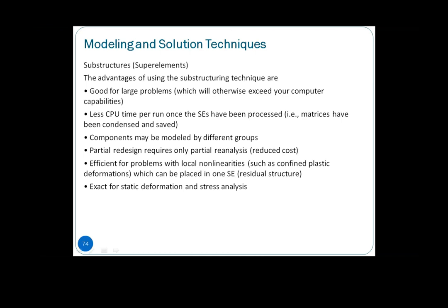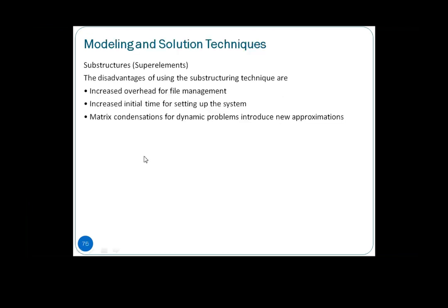So it will be good if you are looking into static deformation and stress analysis. If you are using subcomponents, they can be separated quite well and analyzed separately, individually. But there are disadvantages also of using this substructuring technique. So you need to manage more files. Each component, maybe you have one file. So if you have many components, then you have to manage all these files.